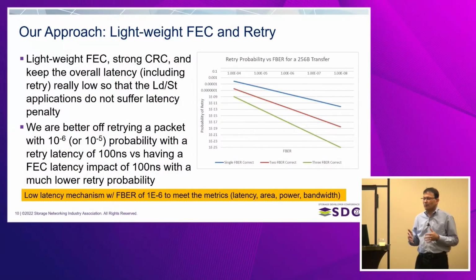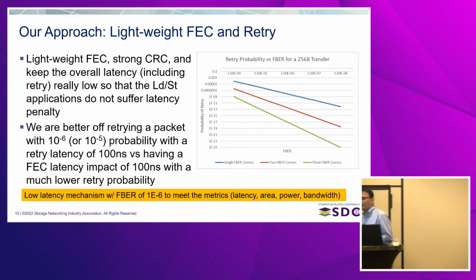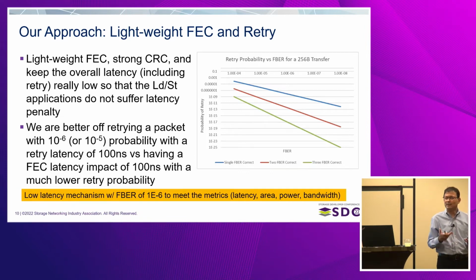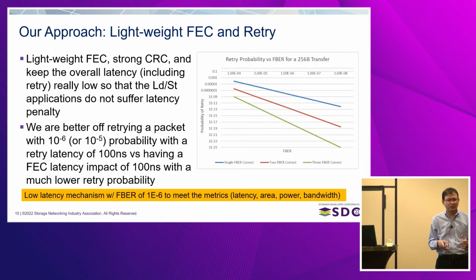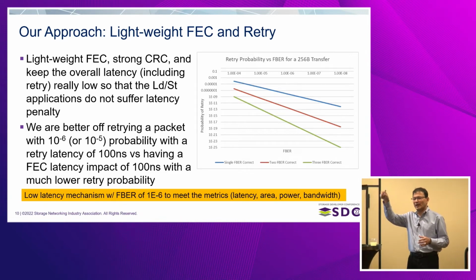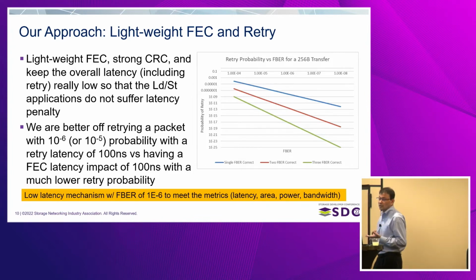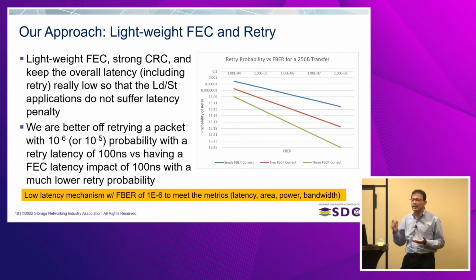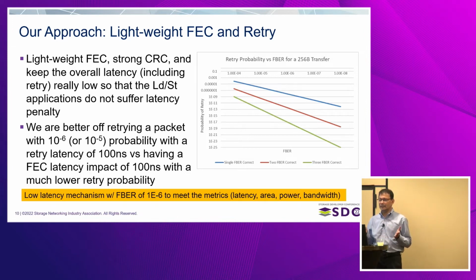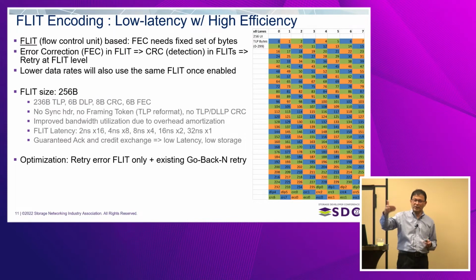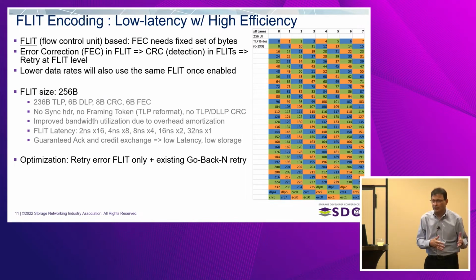CRC, I wanted a very strong CRC, but what do we know about CRC? CRC is a linear problem. By that, what I mean is that I generate the syndrome. It's a division thing, fine. I've been doing CRC, which is a division. No problem, we all know how to do that. But at the end, how do I know something is correct or wrong? All that I look for is, is it 0 or is it non-zero? I'm not trying to look at that syndrome and figure out which of these n choose x, 2 to the power 8 to the power x is wrong. I don't care. All that I know is something is not right. If something is not right, I just ask for a replay, right? So, lightweight FEC, but very strong CRC, and a maniacal focus on keeping latency low. Those are the key things that PCI Express has. And again, that's critical because of the nature of the load store memory-based kind of interconnect that PCI Express as well as similar load store interconnect protocols are.